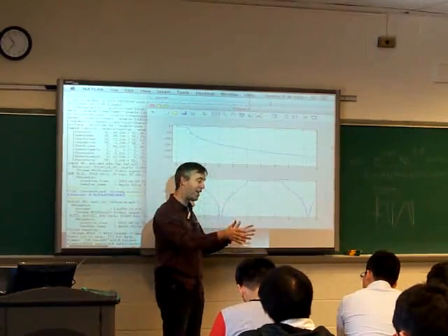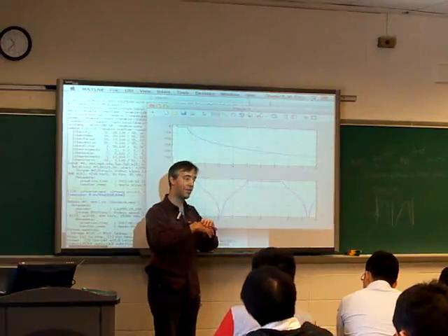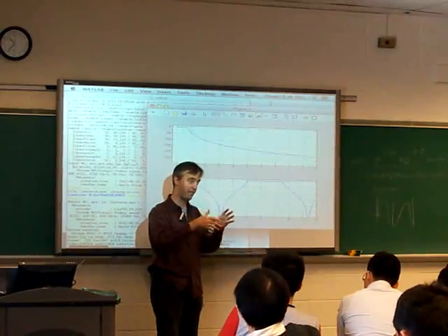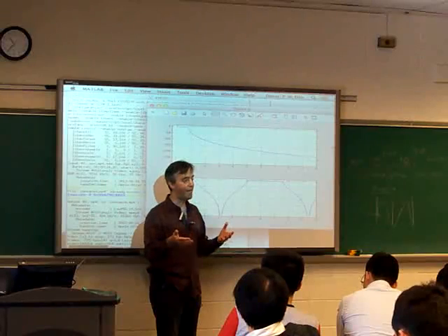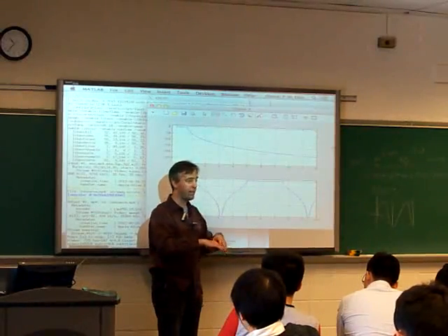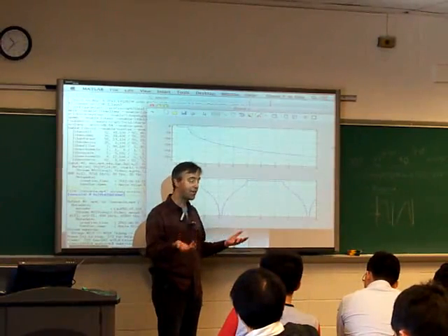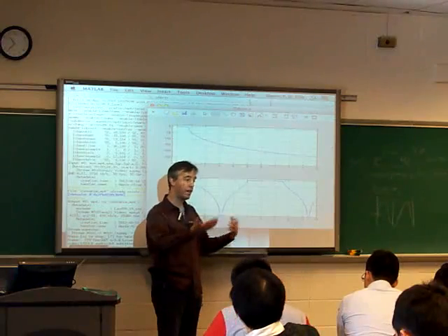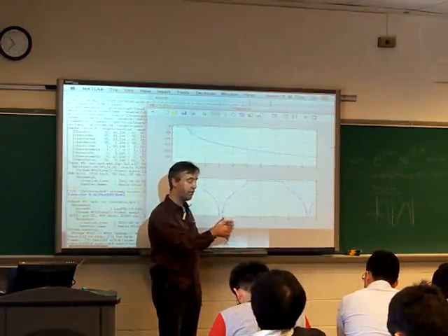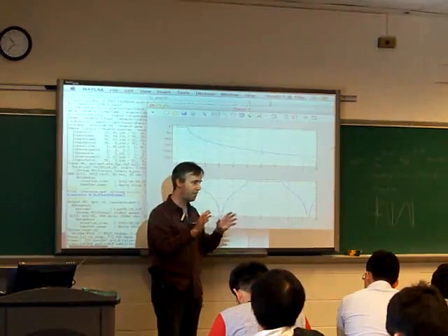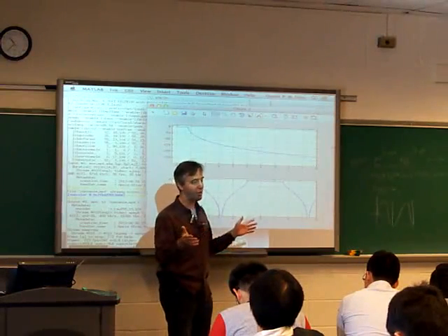If we're sampling at 8 kilohertz and we're trying to select for some signal that's up above half of that, above 4 kilohertz or 8 kilohertz, 16 kilohertz, if we've done our anti-aliasing filter right, then it'll be filtered out before we even get into the discrete time domain. And if we haven't filtered them out in the anti-aliasing filter, then they're going to be aliased along with these baseband components, these components between 0 and 4K. So either we have to make sure that there's some reason why the aliases don't matter, or we're in trouble.